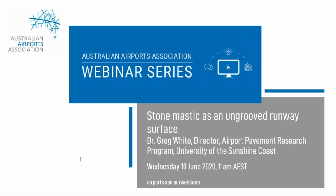Thanks for that, Greg. The next question is from Daryl, and he says, hi Greg, on the SMA performance you showed texture depth of 1.4 millimeters. Usually the texture gets better over time with SMA, but do you think there is anything that could see this reduced to below the 1 millimeter standard, as a 0.4 millimeter buffer is not a lot?